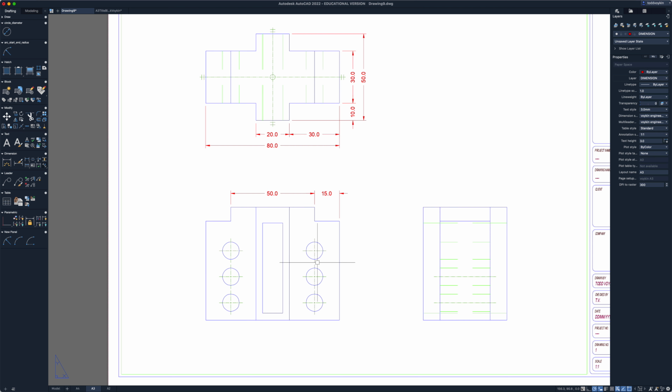I need to get the locations of these holes right here. Now what we have are 6 holes, and they are all following a pattern, and they're all the same size. So again, I'm going to either have to use some type of line of symmetry or TYP, adding that text at the end, annotating it so that it's understood that they're all the same size. So let's go to a linear dimension to begin with, and I'm going to go from the center line.